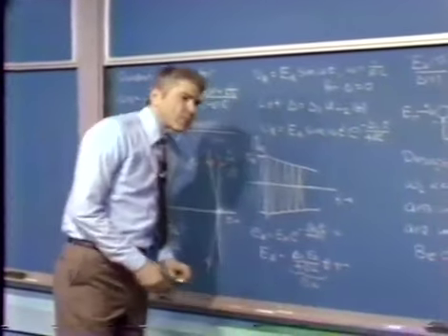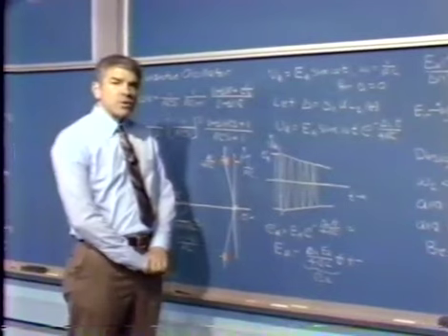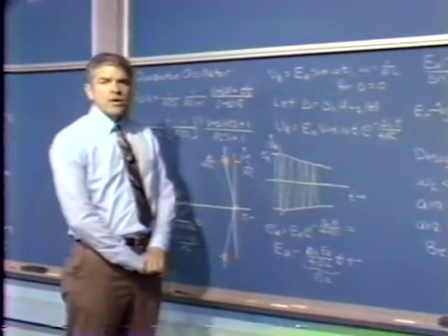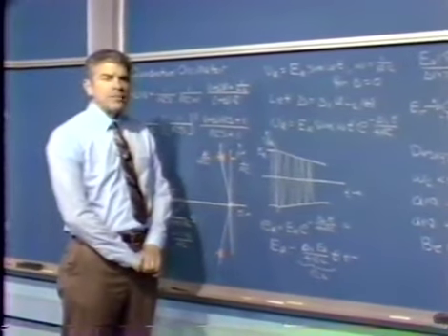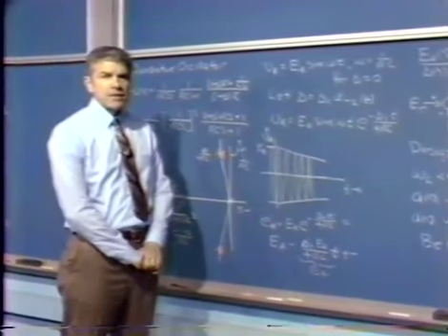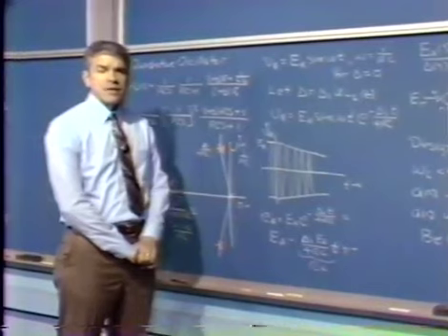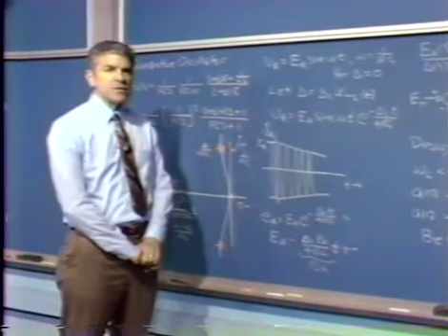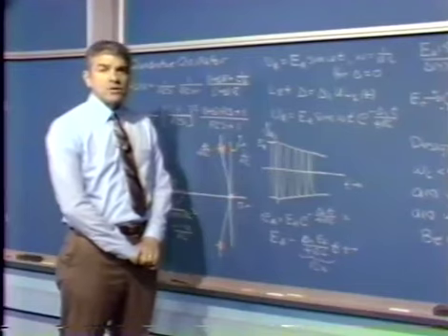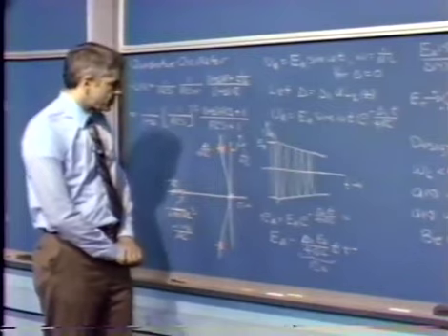One of the interesting fringe benefits of the use of a quadrature oscillator, which is of course where it gets its name, is that when we have the loop running, we ideally have 2 integrators ganged up, and so we get 2 sinusoidal signals. We've been focusing only on VA in the discussion, but we do get 2 sinusoidal signals, which happen to be 90 degrees out of phase, since they represent respectively the input and outputs of integrators. And that is a very useful feature in certain instrumentation applications.